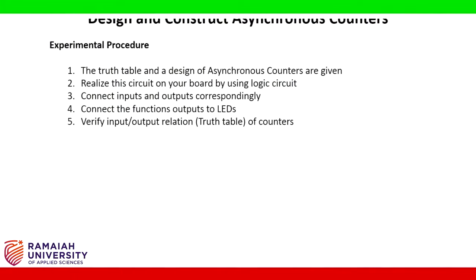Procedure for verification of asynchronous counters. The truth table and a design of asynchronous counters are given. Realize this circuit on your board by using logic circuit. Connect inputs and outputs correspondingly. Connect the function outputs to LEDs. Verify input-output relation, that is, the truth table of counters.